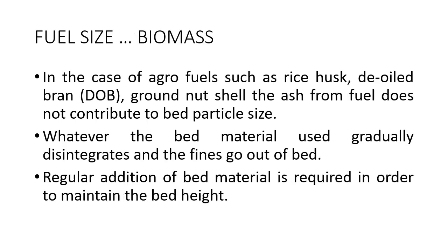Now the fuel size. If it is a biomass, then in case of agrofuel such as rice husk or de-oiled bran, groundnut shell, the ash from the fuel does not contribute to bed particle size. Whatever the bed material used gradually disintegrates and the fines go out of bed. Regular addition of bed material is required in order to maintain the bed height.